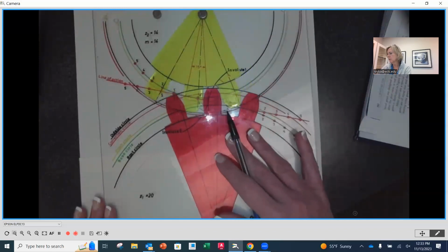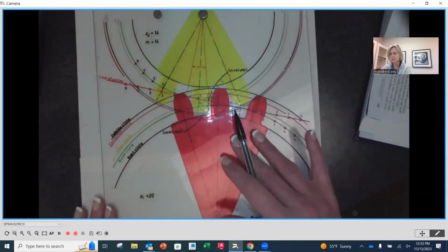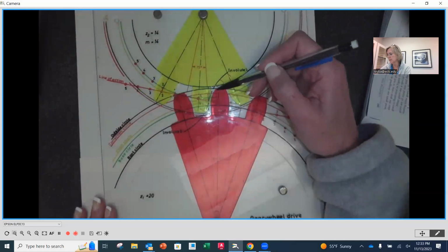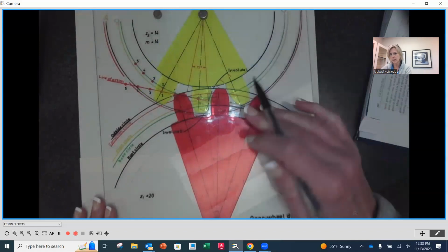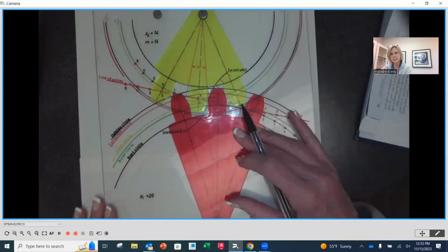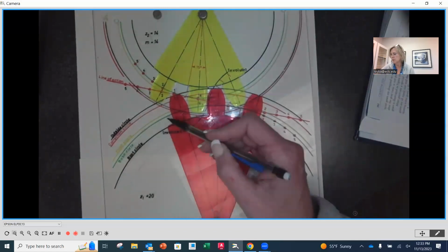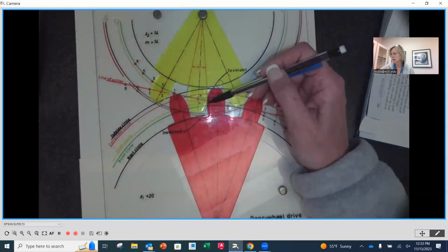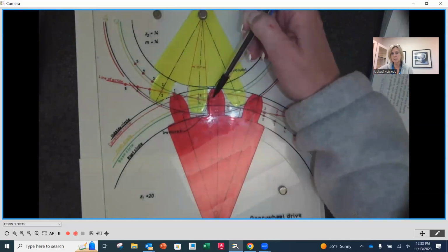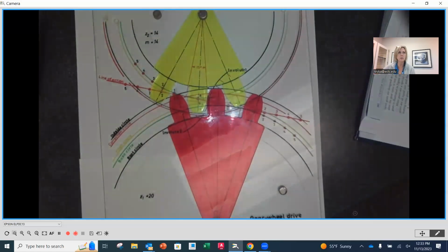Now, as we move along, these are like what I said, the involute tooth. You'll notice that it comes up and has a radius there, and it's always going to hit that very same point. Again, the pitch circle of one gear is tangent to the pitch circle of the other gear. So if we draw them in a layout, we will always show these pitch diameters tangent to one another.